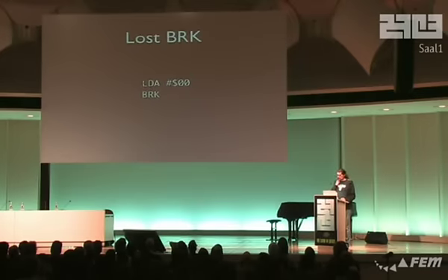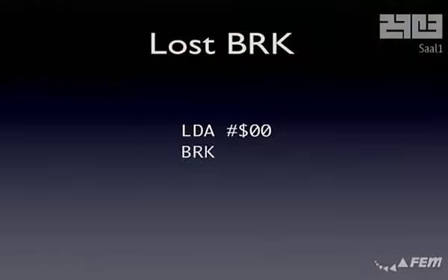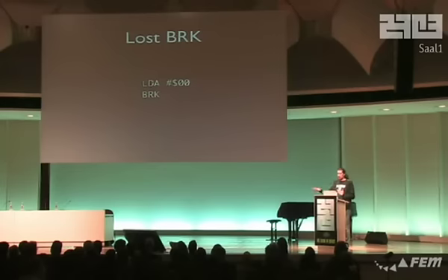This one is a real bug. If you have a break instruction, I mean, you wouldn't have it in real code, but in a debugger, you normally use it for debugging, and you put your break in if you want to know where your code went. But if you have a break in real code and an interrupt happens at the same time, then your break will just get lost. The break will not be done, just the interrupt will be handled.